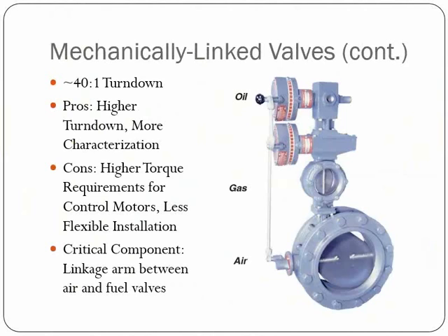If we look at the picture of the control valve assembly that we see here, we have our air valve right on top of our gas valve, which means that when we lay out or design our system, our air manifold and our gas manifold have to run parallel to each other and within a few inches of each other, at least at that portion of your system.